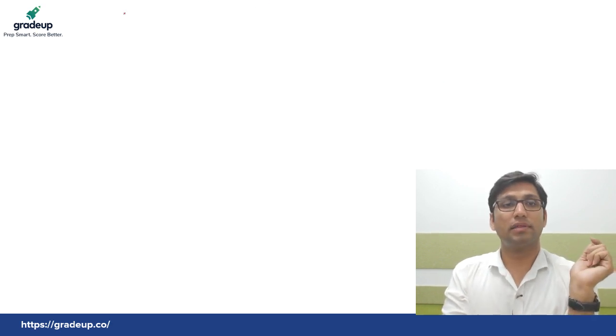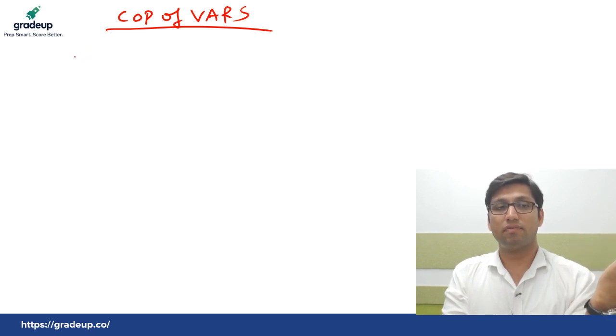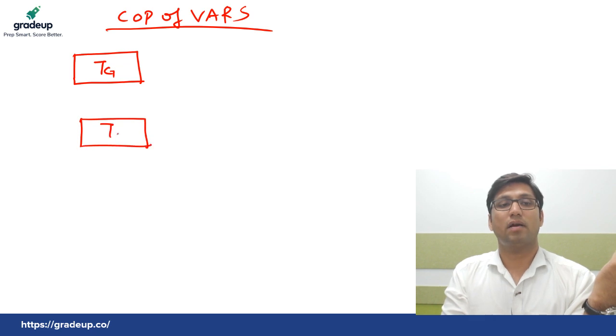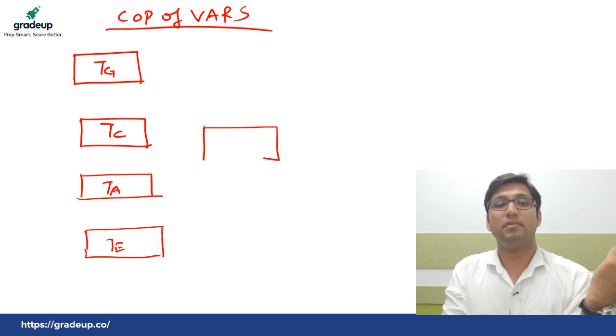Now, if we talk about the COP of a vapor absorption refrigeration system, basically this system consists of a generator which is having temperature Tg, a condenser, and an absorber. Suppose the absorber is having temperature Ta, and an evaporator which is having temperature Te, and they reject their heat to the atmosphere or surrounding.